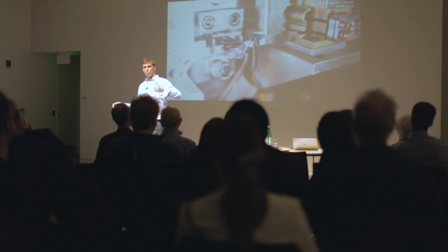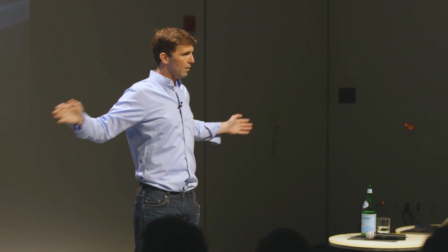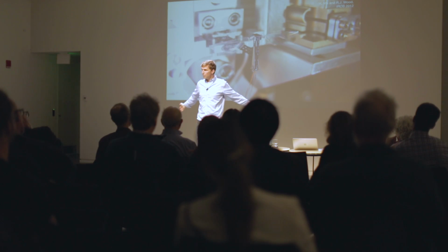And so then I can do force modulation independently on each wing to create body torques. The way I do that is, if I have a larger amplitude on one side than the other, then I have a larger force on one side than the other, so I do this, right? And if I bias my motion fore or aft with respect to the center of mass of the robot, then I get a pitching motion.